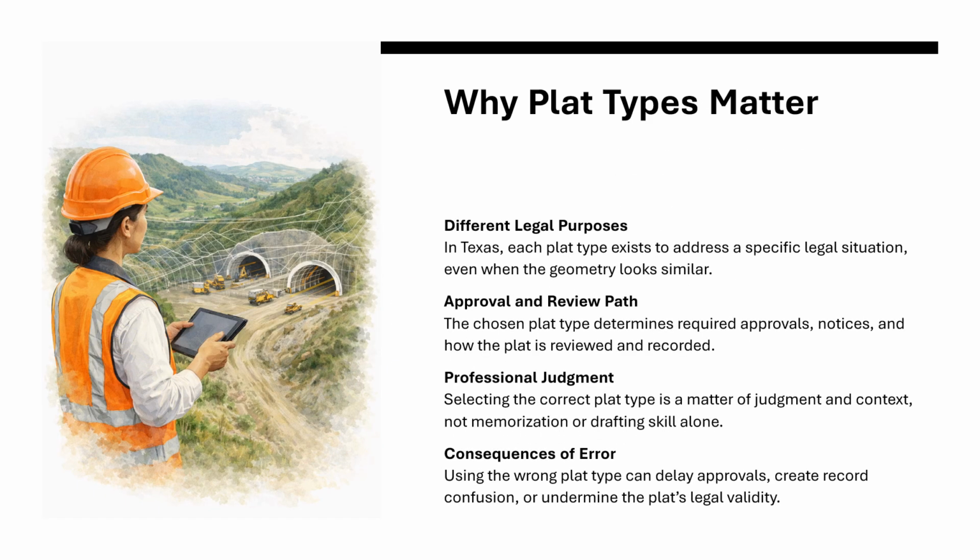Once you understand when a plat is required, the next question is not how to draw it, but what kind of plat are you actually preparing? That distinction matters far more than students usually expect. In Texas, not all plats serve the same legal purpose. Each type of plat exists because a different problem is being solved. Some plats create new lots, others modify existing subdivisions, and some correct errors in the public record, while others undo plats entirely or dedicate land for public use.